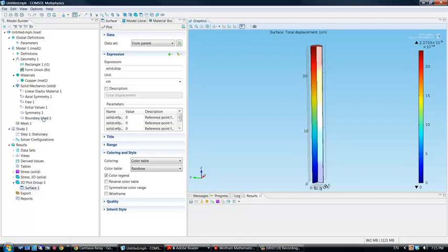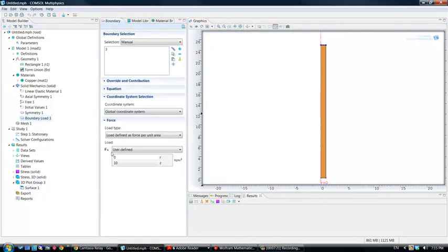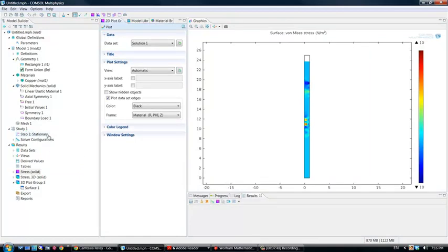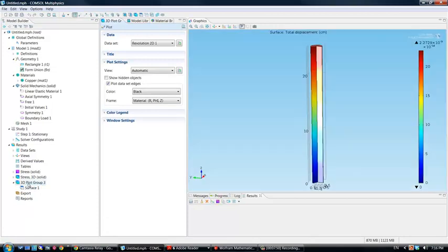But now I'm going to repeat this, except with the load in a compressional direction, I'm sorry. So I'll just simply add a negative, a negative Z direction, to my force or my pressure, and I'll compute that. And you can see here the blue is, in this case, the rod is compressed as well. And you can see here it's displaced as well. So there you go.